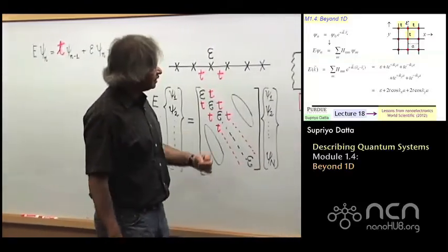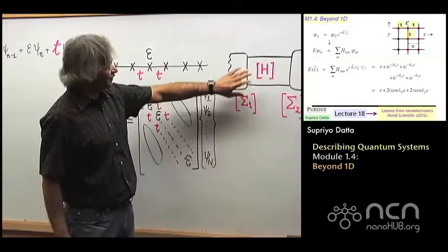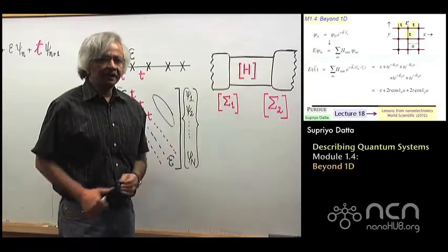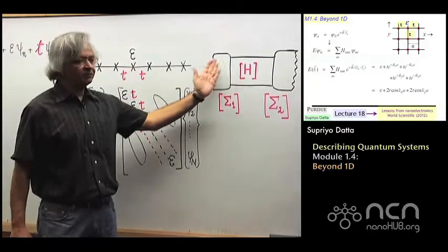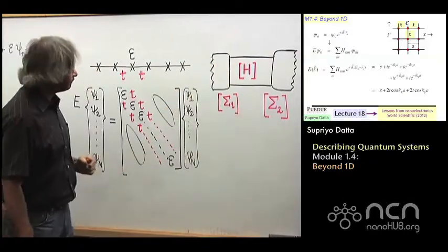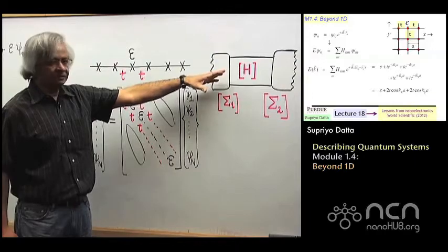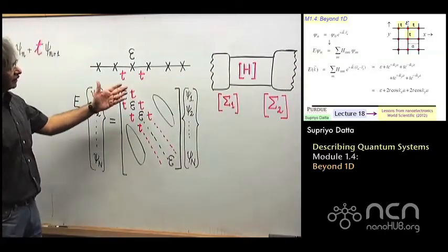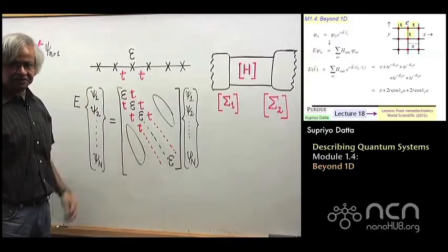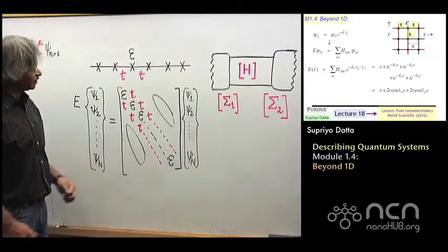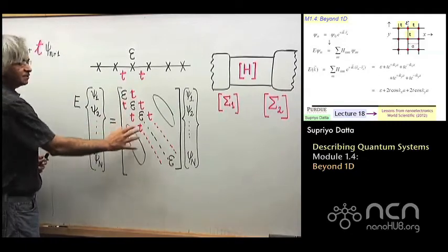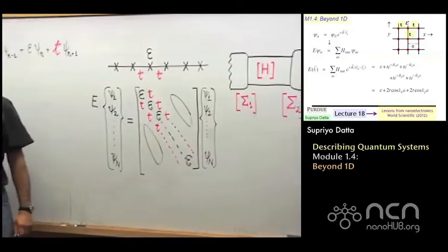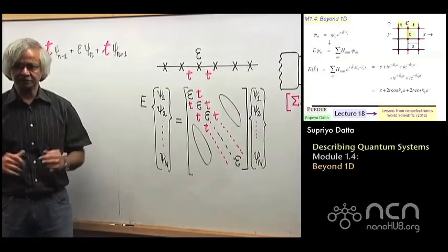The idea is that, as you know, we are trying to write down this H matrix that we can use to model the channel, and if you have a uniform channel, uniform material, then corresponding to a particular matrix which is uniform, we can obtain a dispersion relation, this E-k relation, and then you can adjust the elements of this matrix so that you get the dispersion relation that people believe in, from years of theory and experiment.